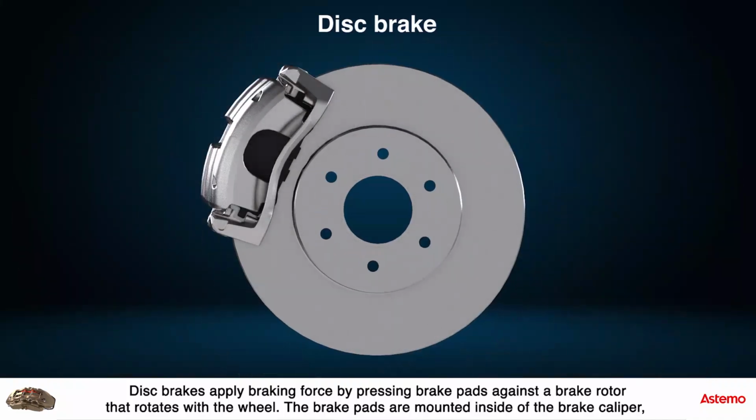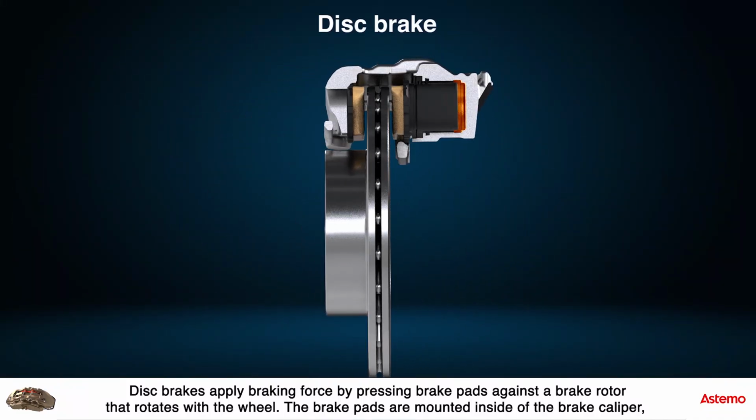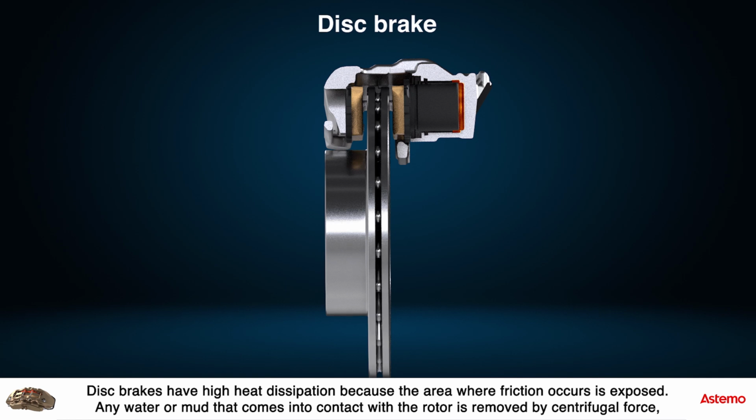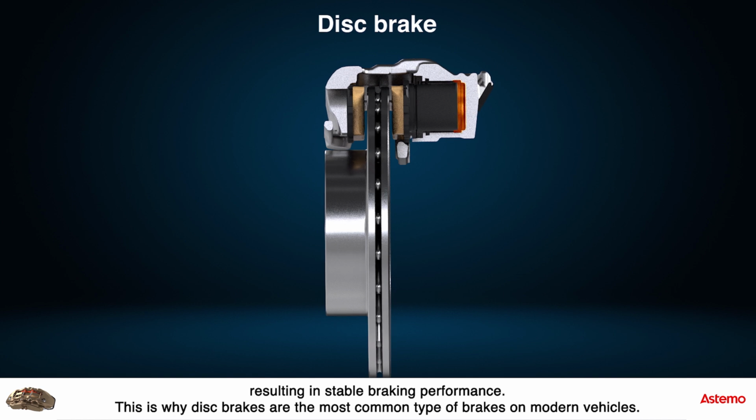Disc brakes apply braking force by pressing brake pads against a brake rotor that rotates with the wheel. The brake pads are mounted inside of the brake caliper, and hydraulic pressure moves the piston inside the caliper to press the brake pads against the brake rotor. Disc brakes have high heat dissipation because the area where friction occurs is exposed. Any water or mud that comes into contact with the rotor is removed by centrifugal force, resulting in stable braking performance. This is why disc brakes are the most common type of brakes on modern vehicles.